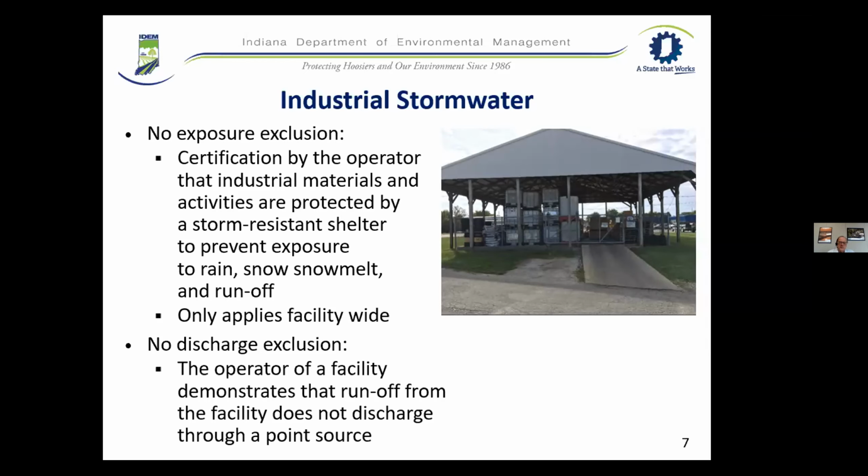Now, if you're in an area like that and you're discharging stormwater into groundwater, one of the provisions of that, we may require there be some kind of pretreatment before it discharges to that infiltration basin. And typically we work this out through local municipal separate storm sewer systems, or MS4s, as they have some requirements and regulations locally. So when we get into those situations, we'll often pull in an MS4 to work with us in doing some kind of pretreatment to protect groundwater, especially if we're in wellhead protection areas.